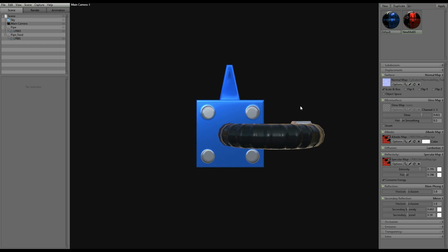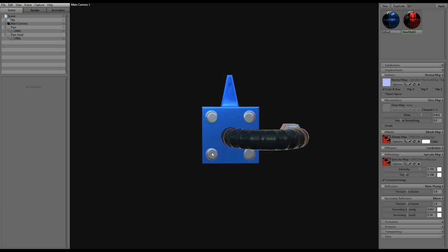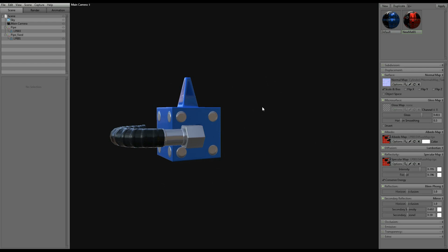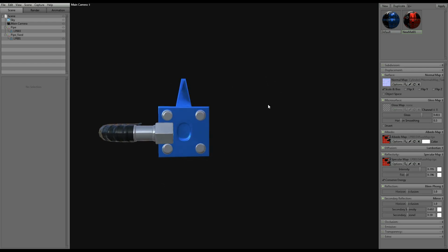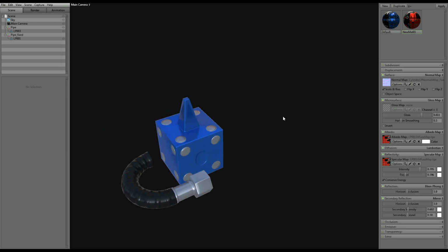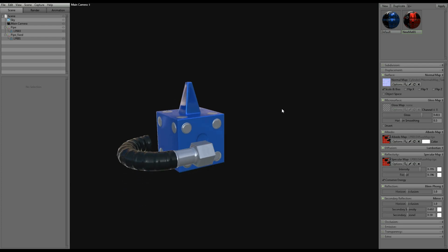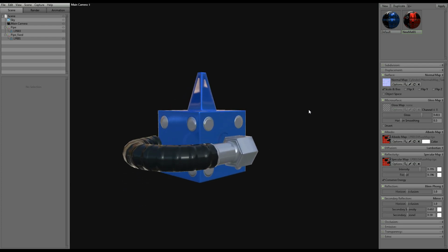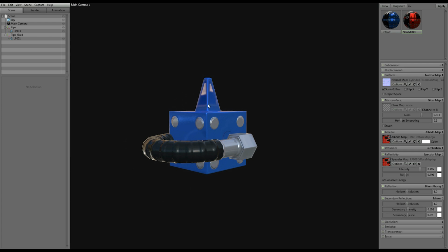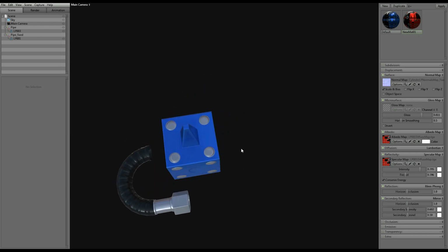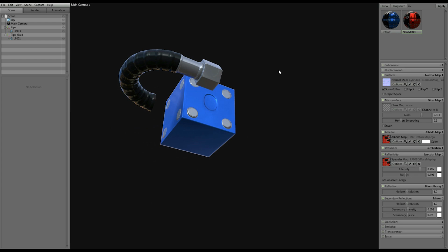Basically, if you take notice, first of all, look at how the high poly floating geometry actually ended up on the top of the mesh, how they're kind of skewed inward. They're all like that, no matter which one you look at, and depending on the camera angle, it can look better or worse. There's also an issue up top where the normals are trying to run across the edge of the peak here. So that's what would happen. This is pretty common when you're doing something like this.